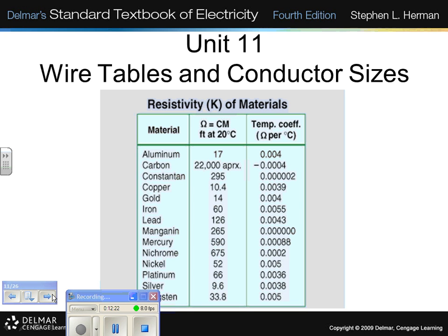So anyway, even though it says 10.4 here, I want you to write this down. The copper coefficient that we will always use will be 10.8. I believe Singer, Foster, and Bertrand did some research and realized that the table starts derating at 30 degrees centigrade, and reversed the calculation and said, oh, that should be 10.8, not 10.4. And I agree with them totally, even though they never said that out loud. Okay? So there we go.